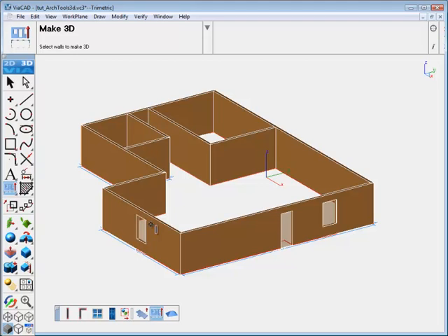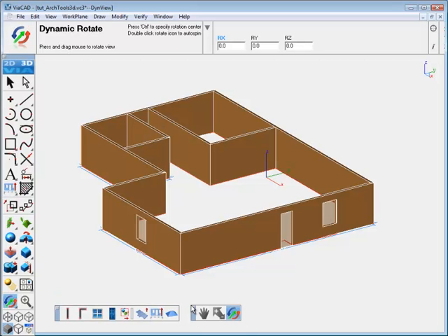We'll adjust the view just a little more to center the drawing. We'll pull off the navigation tools to give us quick access to them later. Next, we'll add a floor slab. Click the Slab tool from the toolbar.